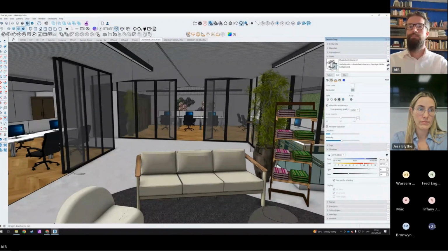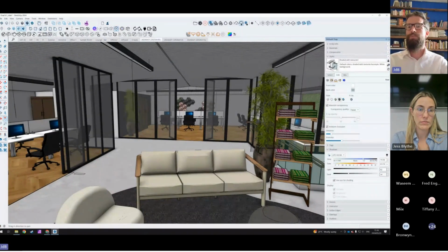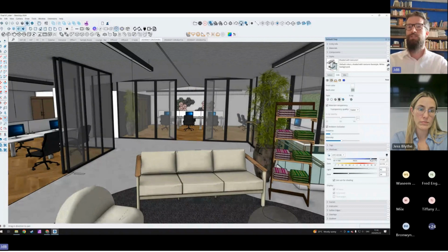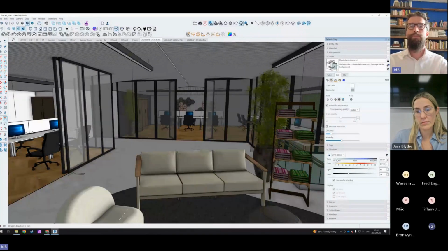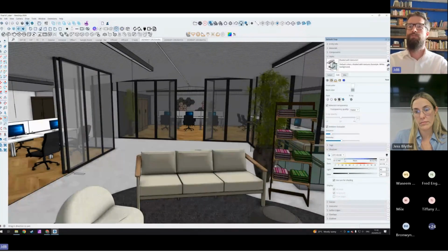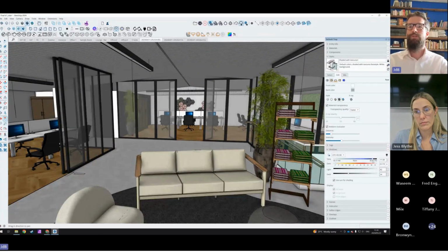So let's get a little bit more of morning light in the scene. Even though the roof is closed, we can see how the shading is changing. And however warm or cold you want this to look, you can then play around with the overall lighting and the ambient occlusion turned on. So that is all visible to us before we even get to the V-Ray toolset.